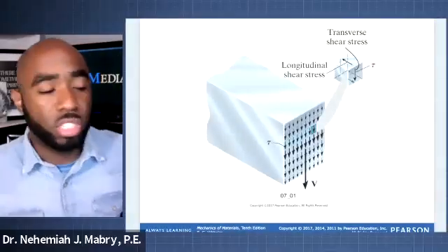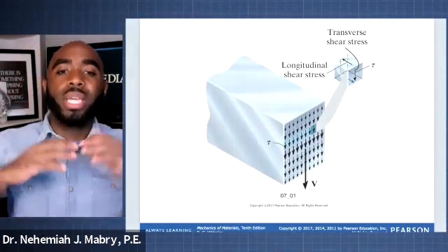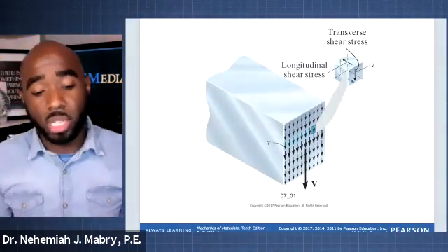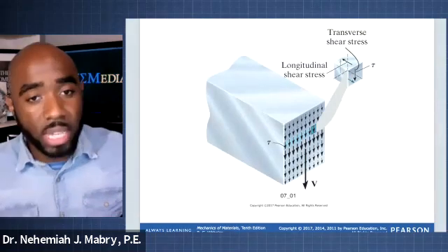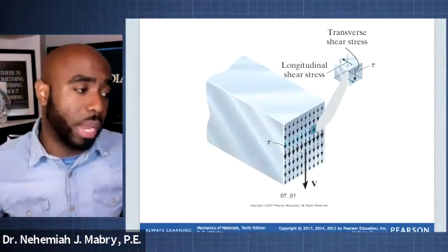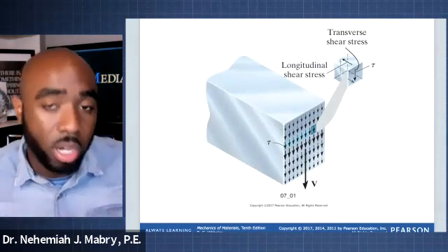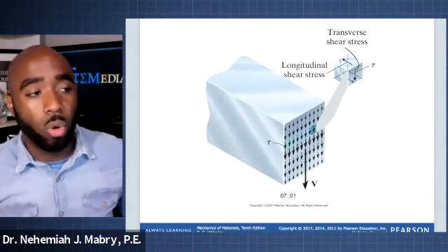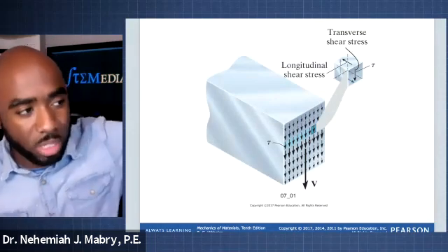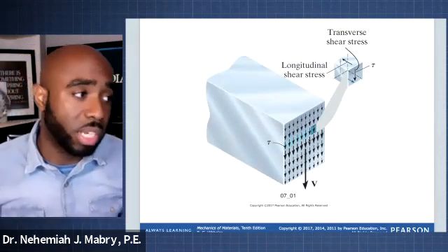Let's talk about this idea of shear. We were talking about bending moments and bending of beams in our last lecture. I'm going to share the screen with you. When we think about the shear that is happening across a cross section, I want you to understand that this shear force that we often solve for is a shear force being experienced across the entire cross section, or distributed, if you will. This force is being distributed across the entire cross section.